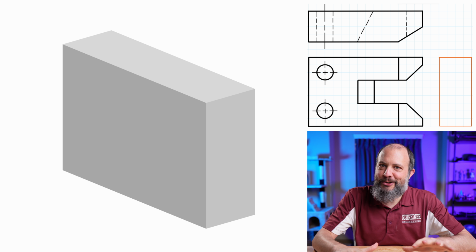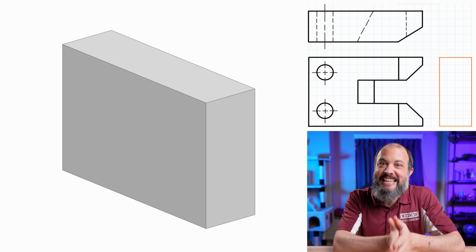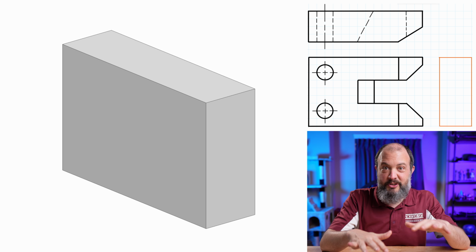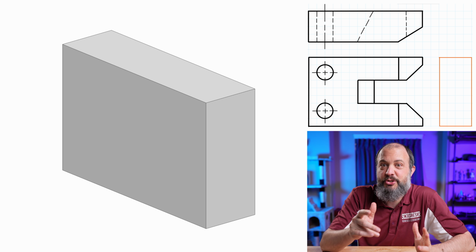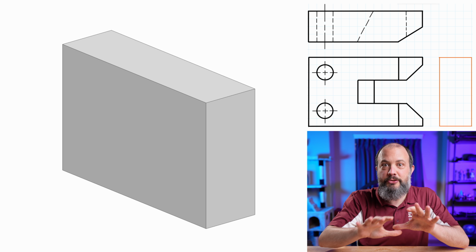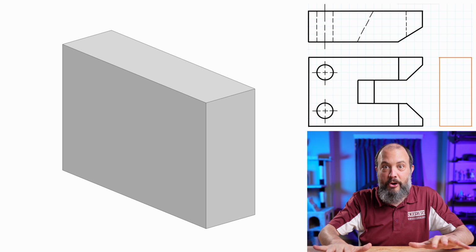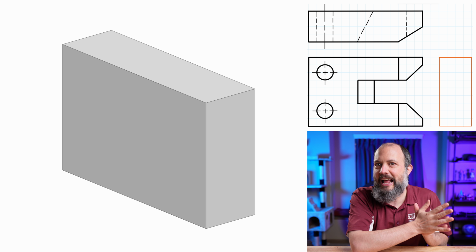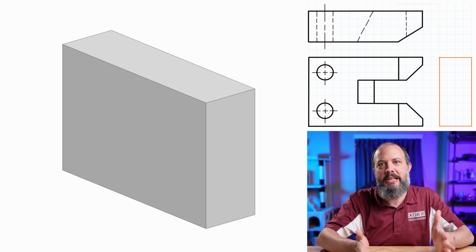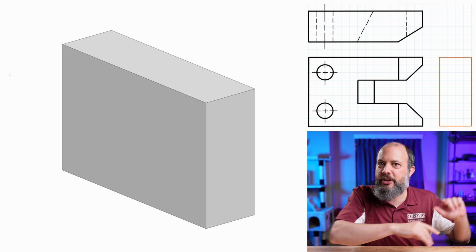And what you'll immediately notice about this drawing is that there are now inclined surfaces. So inclined surfaces are actually extremely useful and really kind of easy when it comes to drawing these missing views. I do have another video about missing views where you just use the 2 views given to draw the third view directly, and it has a great explanation about how to use inclined surfaces to do that as easily as possible.